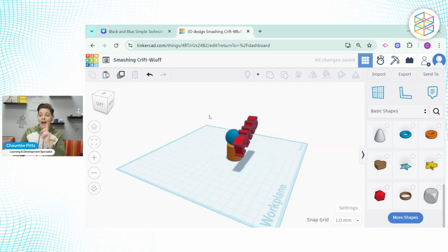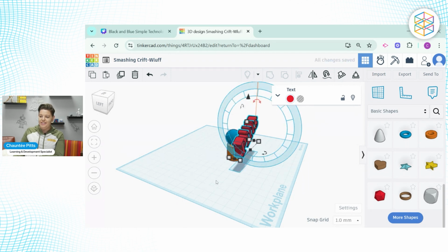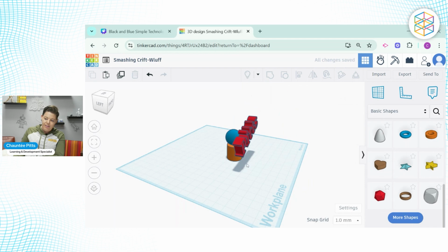Here's the part that I personally got really frustrated with because I didn't understand why it was doing that. You'll notice that these little tick marks are how it jumps, and I'm like, I don't want it to turn that much. What I didn't realize is if you move your mouse up where it's not inside of this area, then it lights up and lets you do slow rotations, which is a game changer when you're trying to make little rotations. You can see the shadow underneath there, so you know that it's above the build plate, and that helps the kids visually see if it's not working correctly.